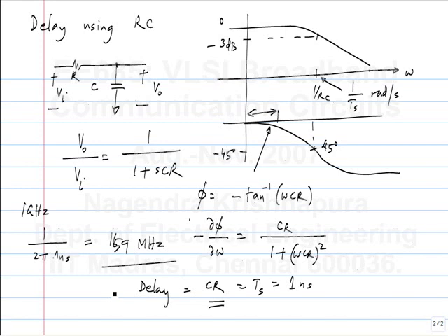RCs give you not only delay but also high frequency limiting, and the high frequency limitations are just too much to handle. If instead of RC you use LC sections, then you can extend the bandwidth. In the limit, when you have infinitely small L's and C's but an infinite number of them, you can make a transmission line which has no attenuation but a uniform delay. When you have lumped L's and C's, it will have some bandwidth, but it will be better than the RC case. That's why you can't use passive RC structures for delaying the signal.